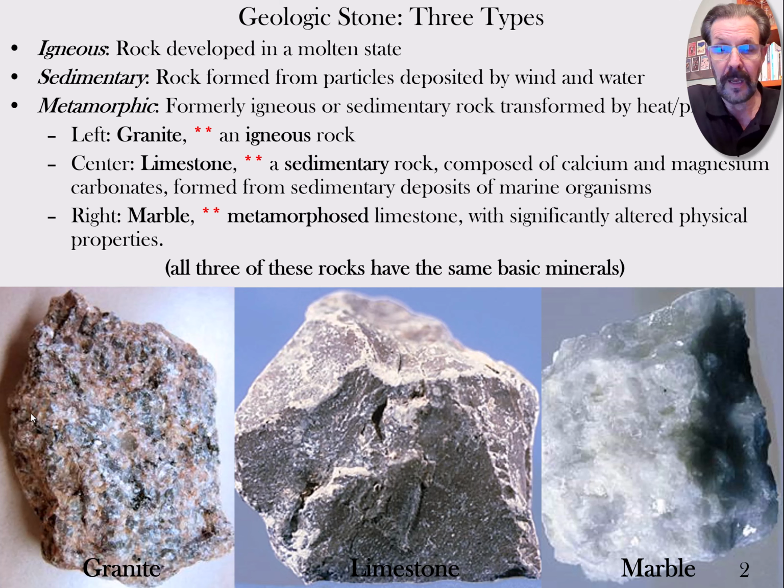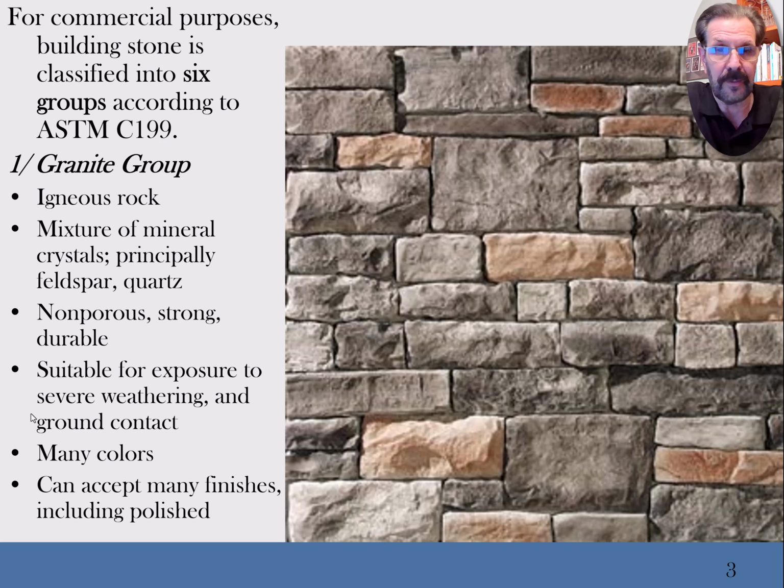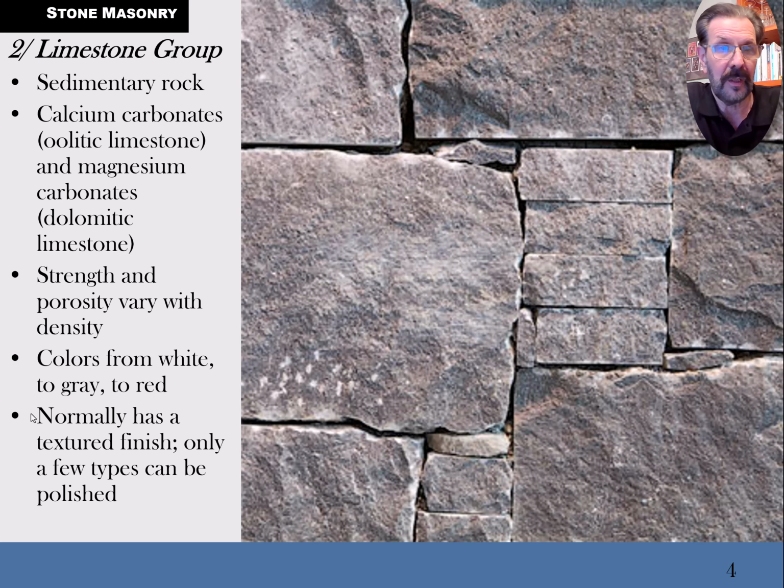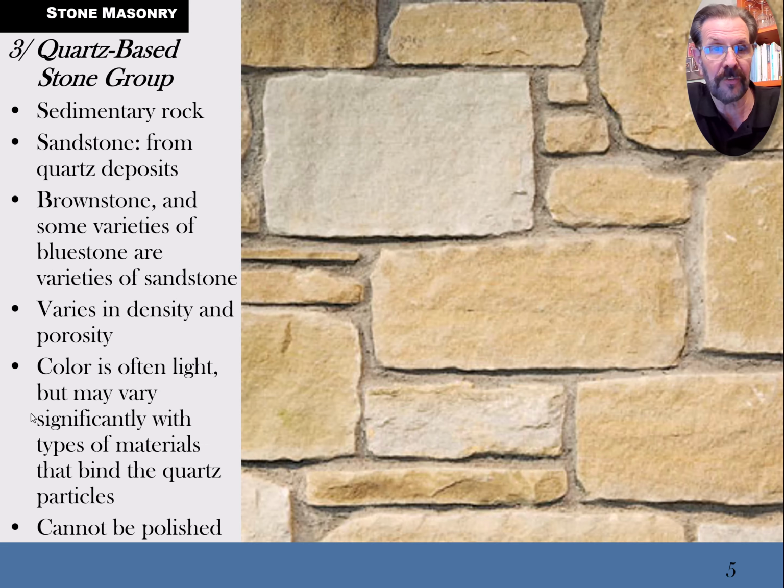Marble is actually something that's even more compact and compressed than granite. So it even absorbs water less than granite does. So granite makes a great countertop, marble even more so, or for flooring or things that are going to stain. I mean, if you spill some ketchup on a limestone countertop, you're in trouble. Granite, not so much, and marble even less so. So that's an important property when you're talking about these different rocks. Granite is less porous; limestone and other sedimentary materials would be far more porous and more likely to stain.